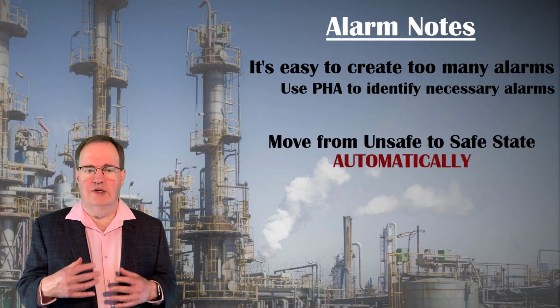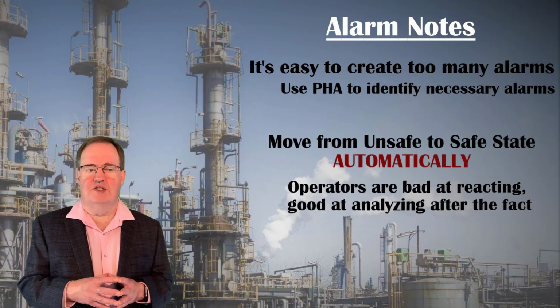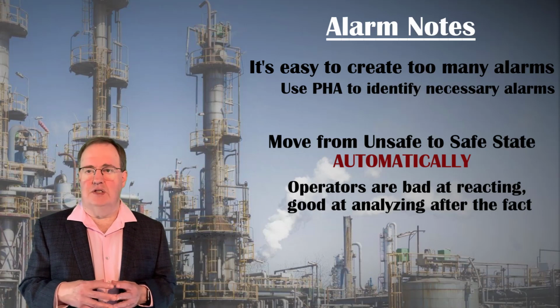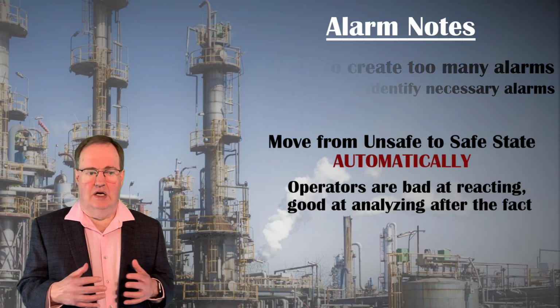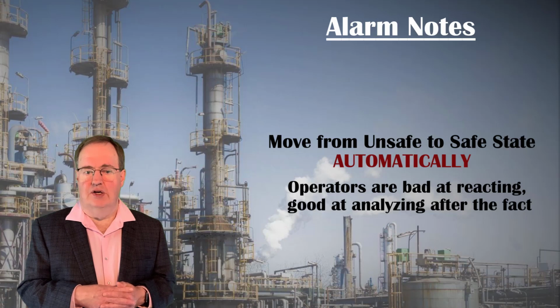On that note, serious hazards should trigger automatic responses. Operators startled and stressed by alarms often can't decide what's wrong or don't follow training and procedures. If you know what should be happening in an unsafe situation based on process measurements, have the automation do it quickly and automatically. Let the operator figure out what's wrong after you're in a safe state. 10 unnecessary automatic shutdowns are much cheaper than one necessary shutdown that didn't happen because it wasn't automatic.